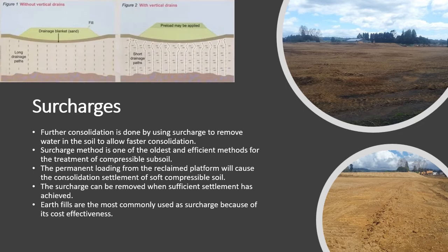Commonly, the combination of preloading and vertical drain is used to make the method more effective. The function of vertical drain is to shorten the duration of soil treatment. Preloading forces water out of the soil matrix, facilitating soil consolidation. Preloading with a vertical drain permits the use of a cheaper, shallow foundation. The soft soil is characterized by low strength and high compressibility, and hence possesses low bearing capacity.